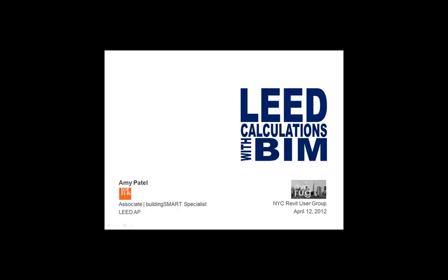I think it's good, the color schemes. There's no way to apply them to different smart ones. No, you can't push them from the template. You can transfer project standards, but not color schemes. Let's say you created a color scheme in one file and want to use it in the next one. You have to recreate it.